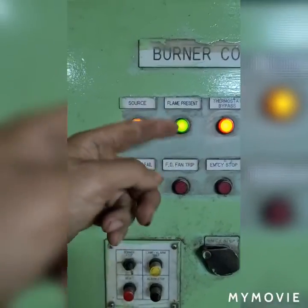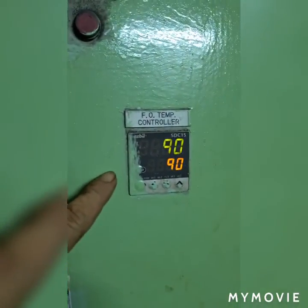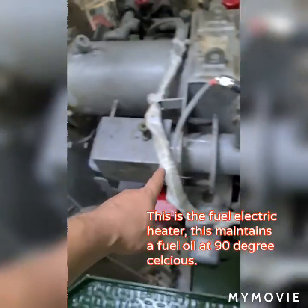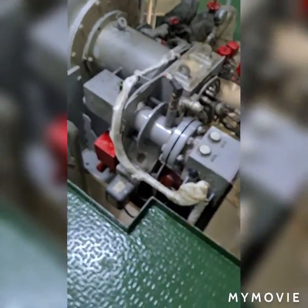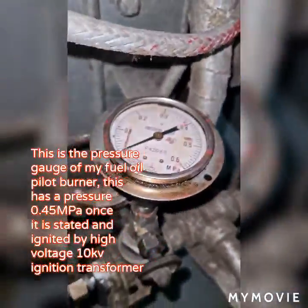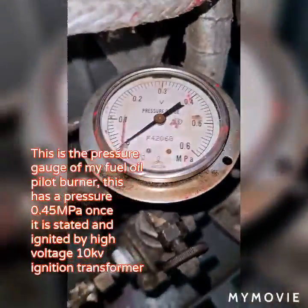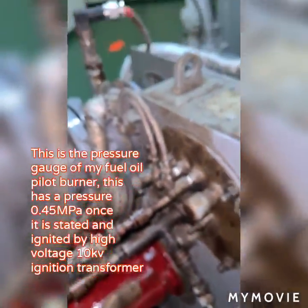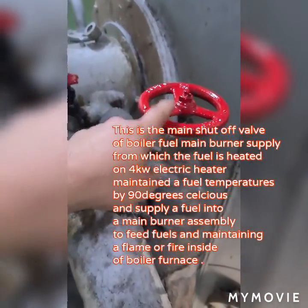Now, as you will see on my burner panel, a flame preset is indicated. The temperature of my fuel is maintained. This is the fuel electric heater. This maintains the fuel at about 90 degrees Celsius. And this is my pilot burner, having 0.45 megapascal pressure once it is started and ignited by a high voltage ignition transformer. It is switched off when the fire is already established.